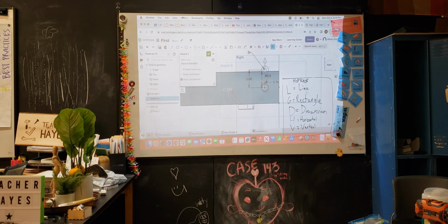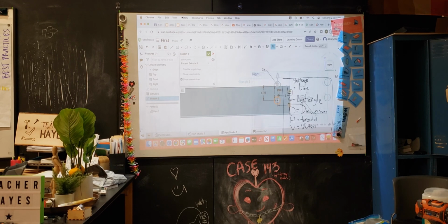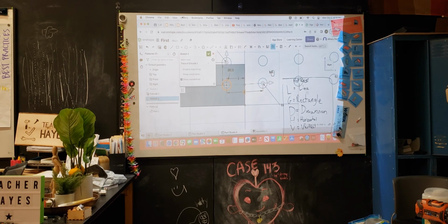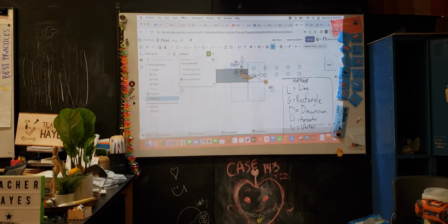So over here, you can specify the number of holes you want to make. So say I want 6. Then over here, using this tool, I can specify the width between each hole. So say I want 2 inches. It'll make 6. Why is it off center? Let me adjust that. Okay, yeah. So I can adjust how many circles I want to make, and I can change this number.